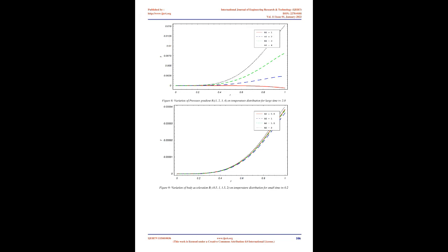Dimensionless parameters are the measure of relative importance of different aspects of the flow. These parameters also reduce the number of experiments, as different properties of the flow or fluids are combined together through these dimensionless parameters to observe their cumulative effect. To obtain the dimensionless model temperature equation, we introduce the following dimensionless temperature parameter. The corresponding initial and boundary conditions in dimensionless form are as follows.